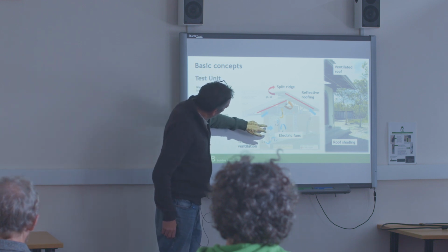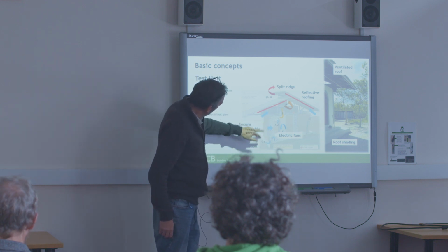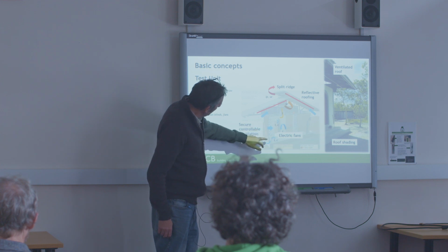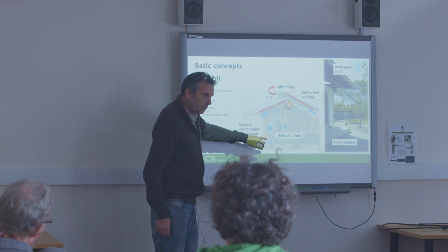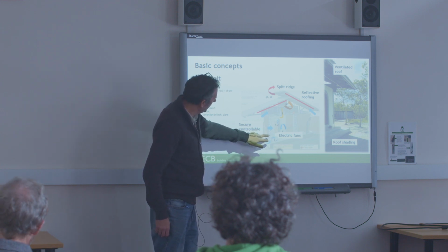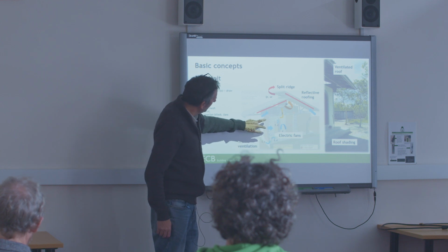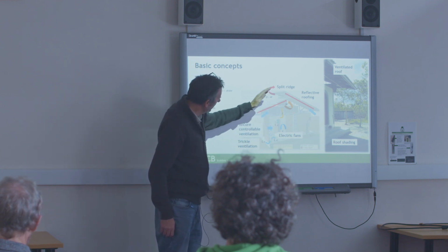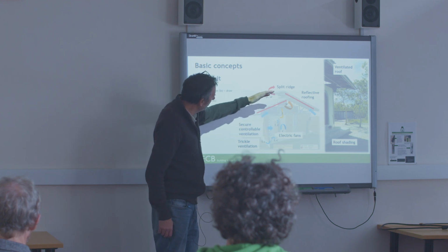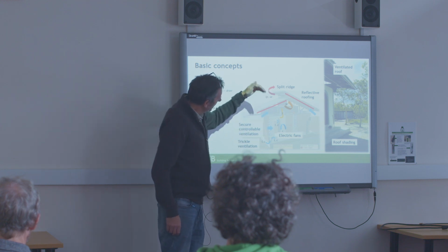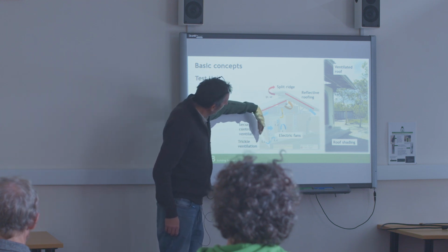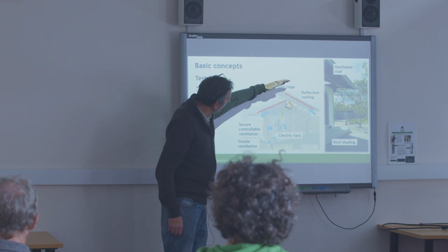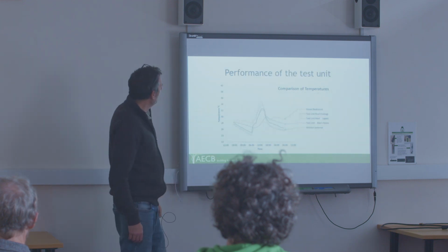So in terms of air movement across the room, we had 3 ways of doing it in this original design. We wanted some trickle ventilation that would always be present. This is a ventilated window seat, and we had the main windows and also holes in the ceiling. And the idea was that would create a stack effect on still days and would allow, on windier days, air to move across the room, across the occupants and out.